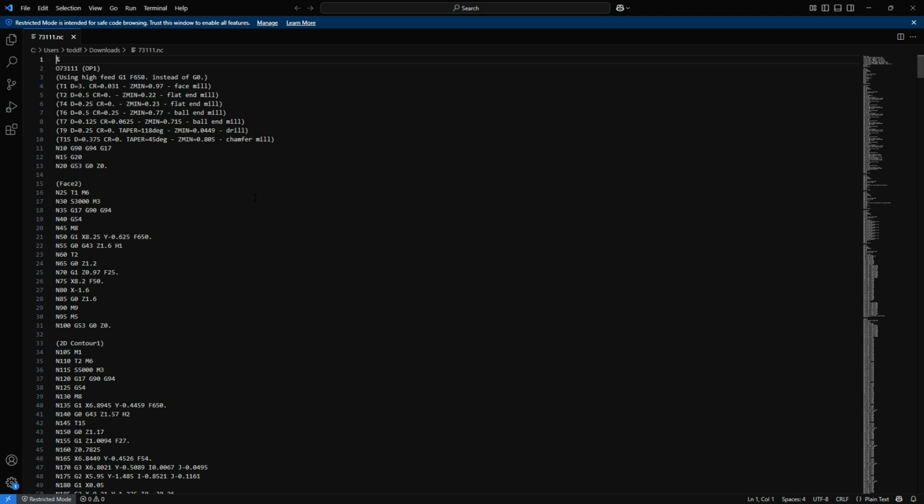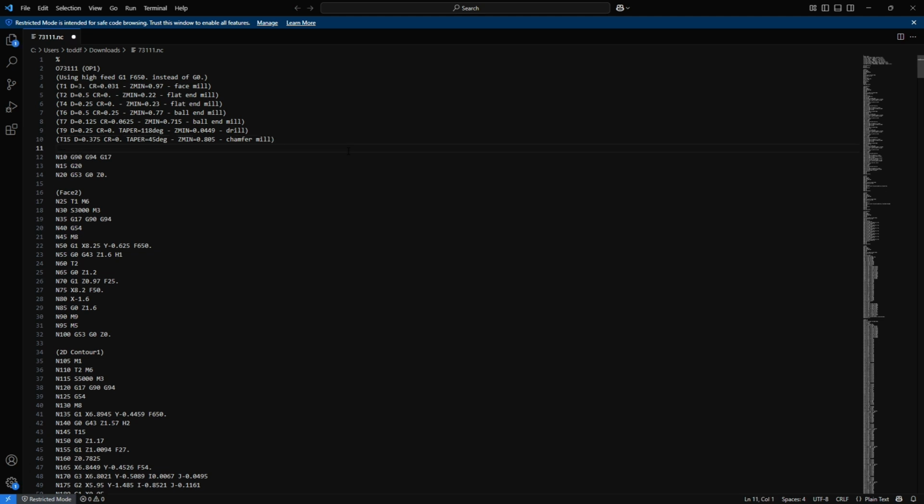If you want to, you can manually edit this. It puts standard notes in here for all the tools. I'm going to put a note in here as operation 1. It's critical to use the right size parallels for all these. So I'm going to hit enter and type a new comment. Make sure it's all in caps and has parentheses around it: use 1.625 parallels. Okay, so that is the height of the parallels. Let's actually put 1.625 inch tall parallels. That way when the operator has this, they have a note there that tells them to do that.